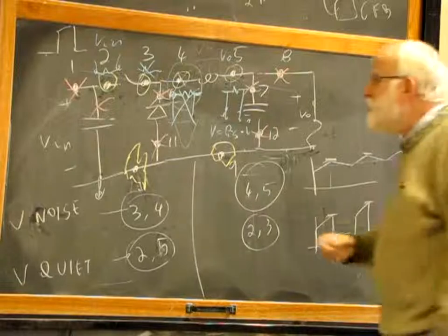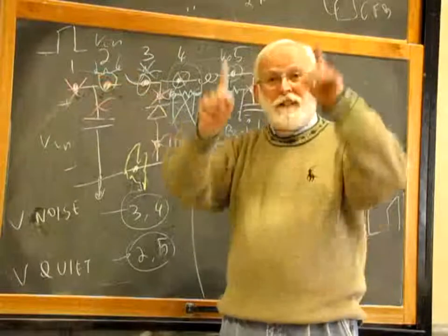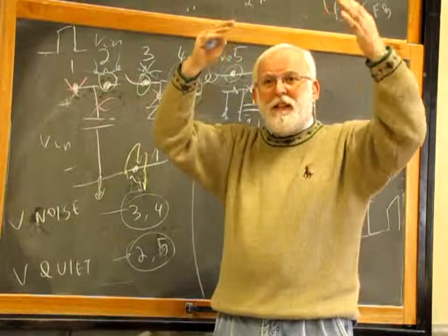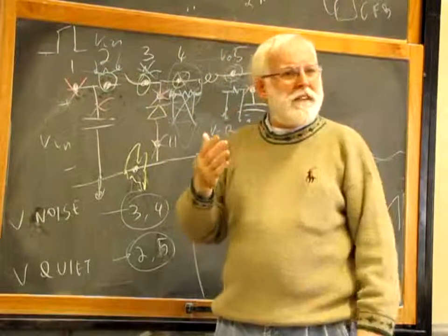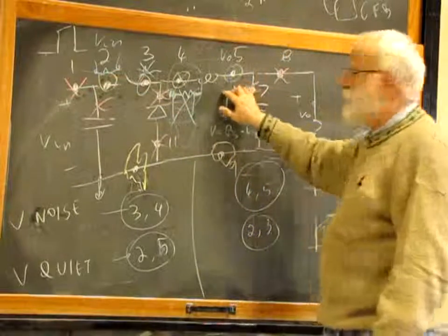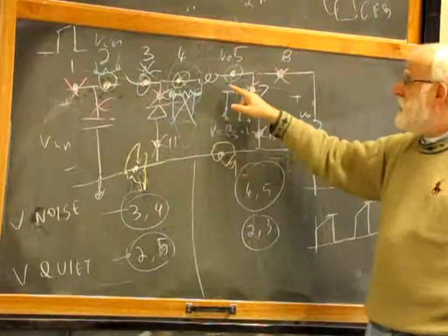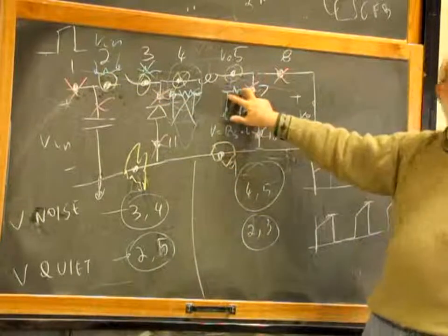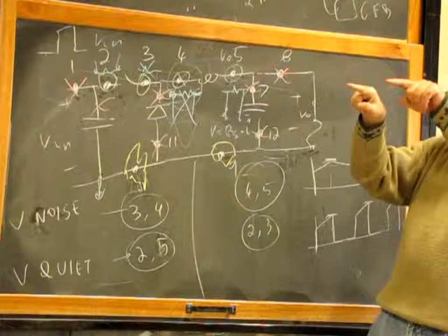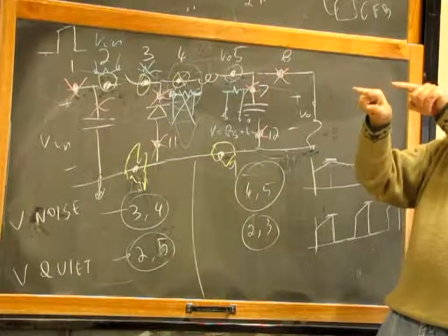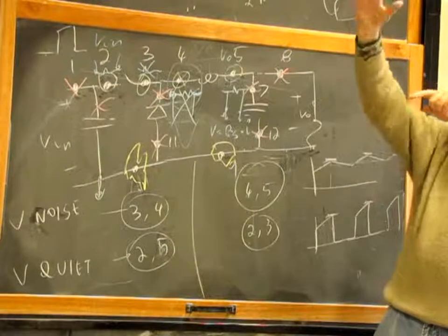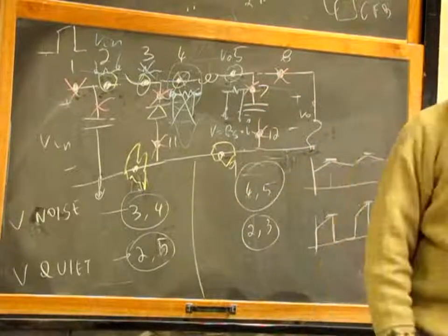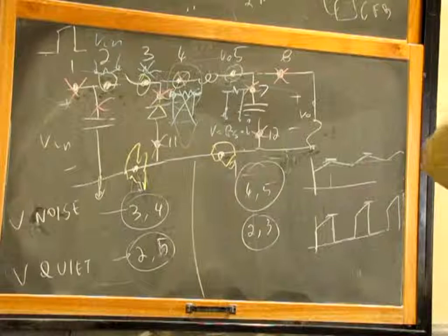So if you come in at 12 volts and you have to go to the 12 volt level to measure a difference of 100 millivolts, it can be done, but usually it's more complicated, more difficult than measuring it over here. Here you have an input voltage of 12 volts, you supply your control system at 12 volts, and here you have, for example, 5 volts. So measuring the difference between 2 voltages is around 5 volts. If your supply voltage is higher, it's easier. Your common mode voltage range does not have to reach the positive range.